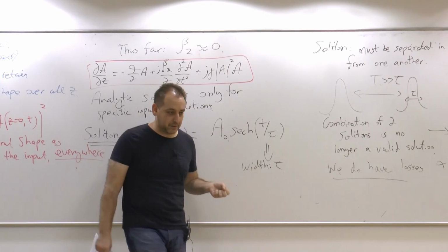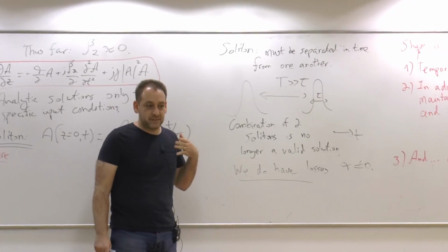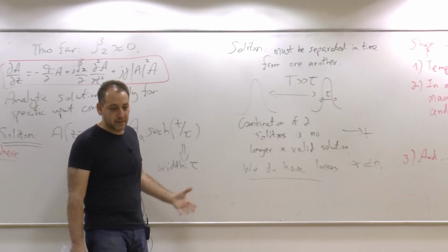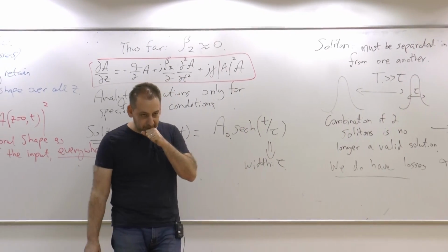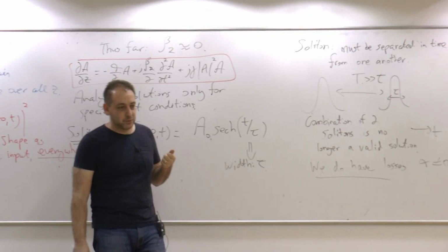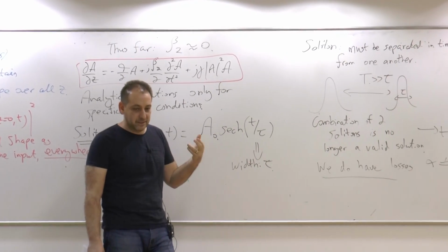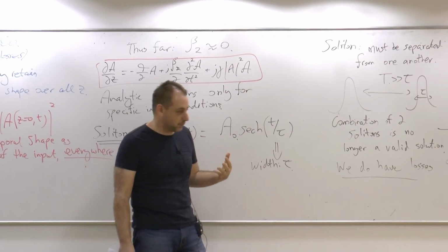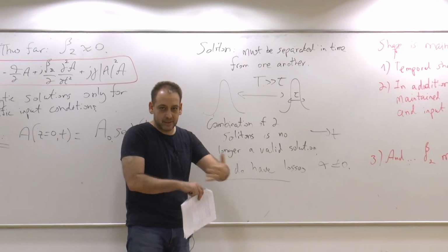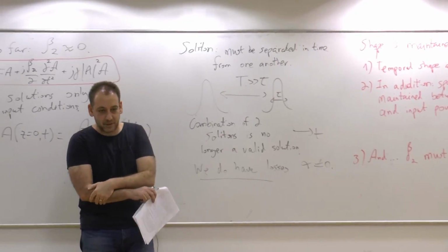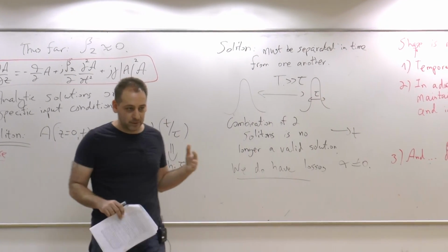In a fiber amplifier, for instance, over a span of 10 meters or 30 meters, you experience a 100-fold increase in power, and this was too drastic. This in itself was enough to disrupt soliton propagation, so point amplifiers like we are familiar with in communications are not a good way to do this.